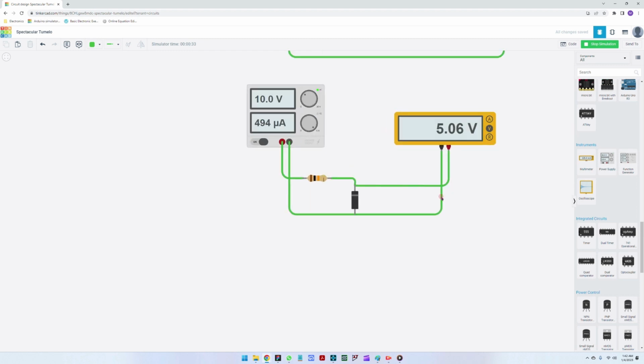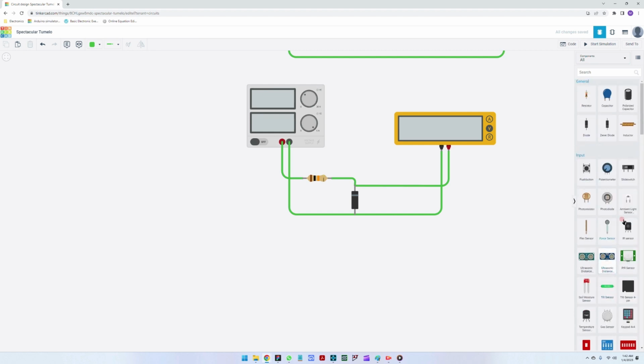Great. Let's do a 3-volt power supply. Let's assume that we need a 3-volt line here. Let me stop the simulation, and we're going to take another Zener diode, rotate it into place so that it's reverse polarized. I repeat this again.